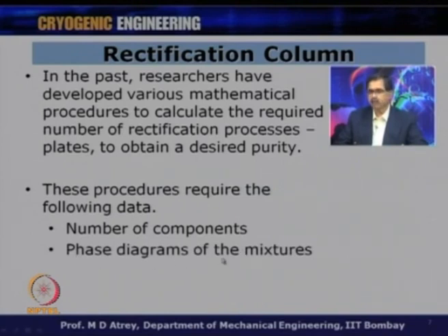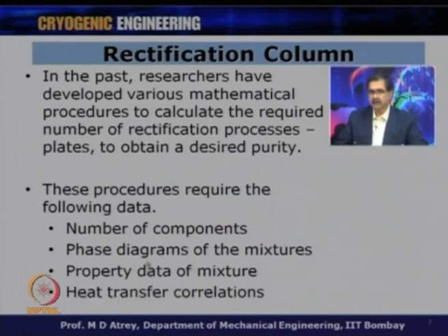So, the more the number of components, the more important it will be to have a phase diagram for this mixture. Also, what is important is the property data of the mixture at lower and lower temperatures, which is also very difficult to get. And ultimately, what is most important is to know the heat transfer correlation, because as you know, boiling and condensation heat transfer is occurring on every plate. So, one needs to have all these validated correlations for this data, which is very, very difficult.